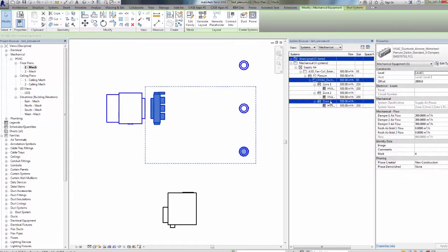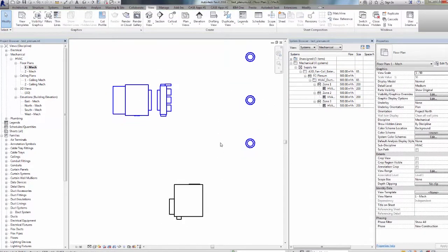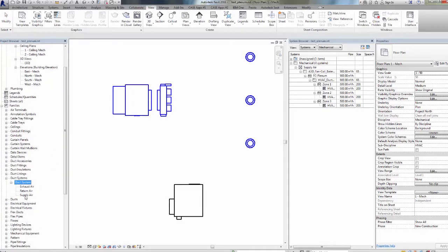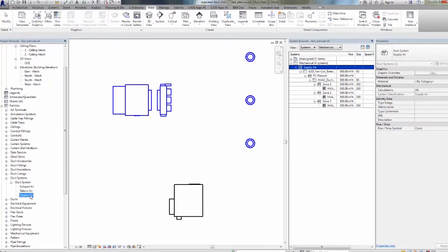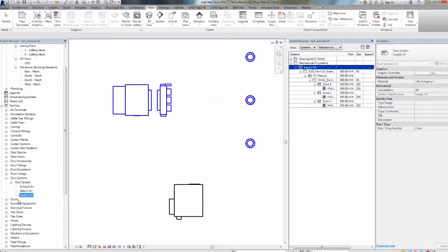If a fresh air system was created, it is highly recommended to duplicate the already created system and rename it as fresh air. So a new fresh air system shall be created from the plenum. We see that two different classifications are created, where fresh air ventilation includes the plenum as outlet and the fresh air unit as machine. We are now creating the physical connections.